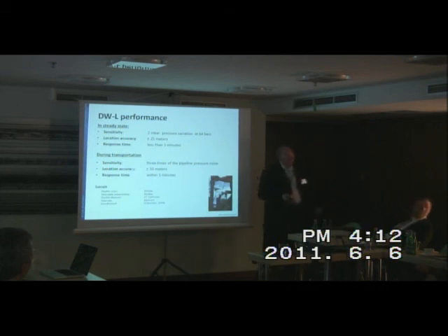Sorry, what's the maximum length or distance between 2 detectors? Between 2 detectors, we like 30 kilometers to be the maximum. Yes, 30. But in several cases we use 50 kilometers between them, if it's not possible to put another sensor between them. We can also use a large distance, but the sensitivity will decrease in this case.